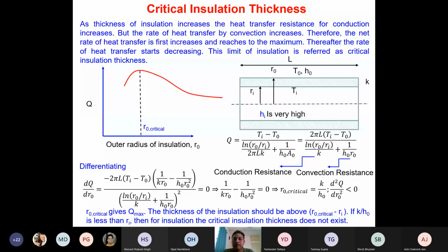So in the last class, we started looking at the concept of heat transfer coefficient. The reason behind that was we argued that conduction is in most of the cases associated with convection, isn't it? So this is one more additional difficulty we have added. As you are aware, we keep on adding complications in our analysis. So the heat transfer coefficient basically gives us the heat transfer which is taking place in a convection mode when there is a fluid.